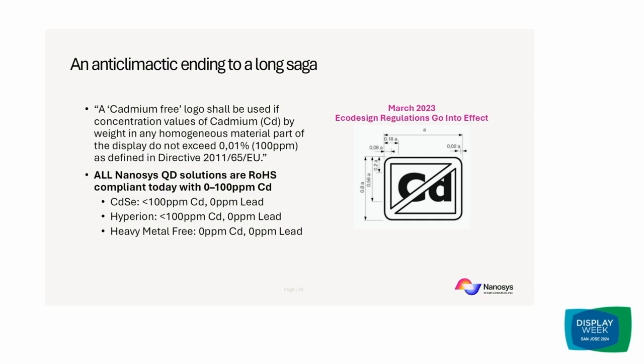So at this point, when you consider the types of applications that are out there with Nanosys quantum dots, all of these are actually, in fact, RoHS compliant. So all of these contain concentrations of cadmium in the homogeneous layer that are less than 100 parts per million in cadmium and do not contain any lead in the system.